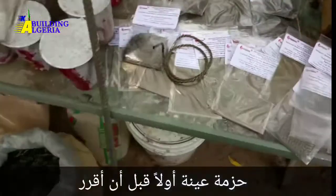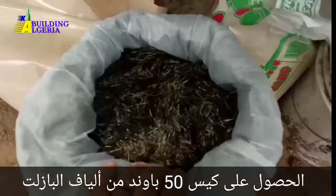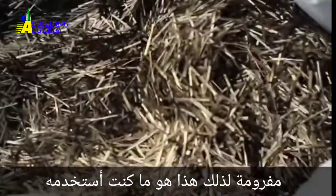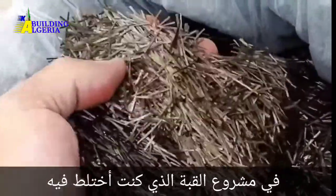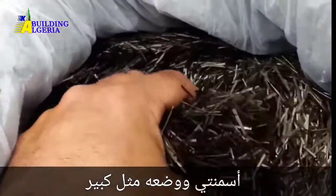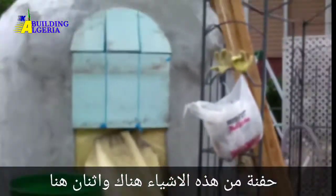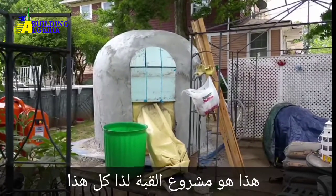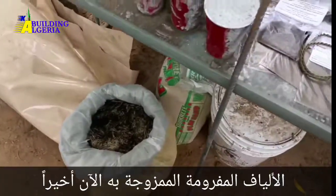I ordered this sample pack first, before I decided to get the 50-pound bag of basalt fiber chop. So this is what I've been using in my dome project. I've been mixing up my cement and putting in a big handful of this stuff into here. So that's the dome project. All the cement you see here has the basalt fiber chop mixed into it.